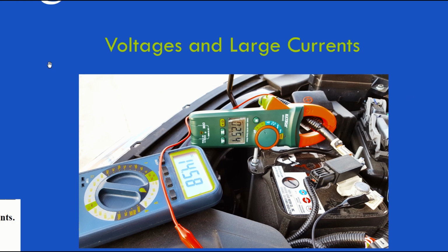different way. So here we are checking the voltage and current on a 12-volt battery in my car. And you can buy these things called clamp meters that you just squeeze this trigger and it opens these jaws up, and then you stick it around this wire and then release the trigger so it's as shown, and it will read out the current. And here it's 2.5 amps.